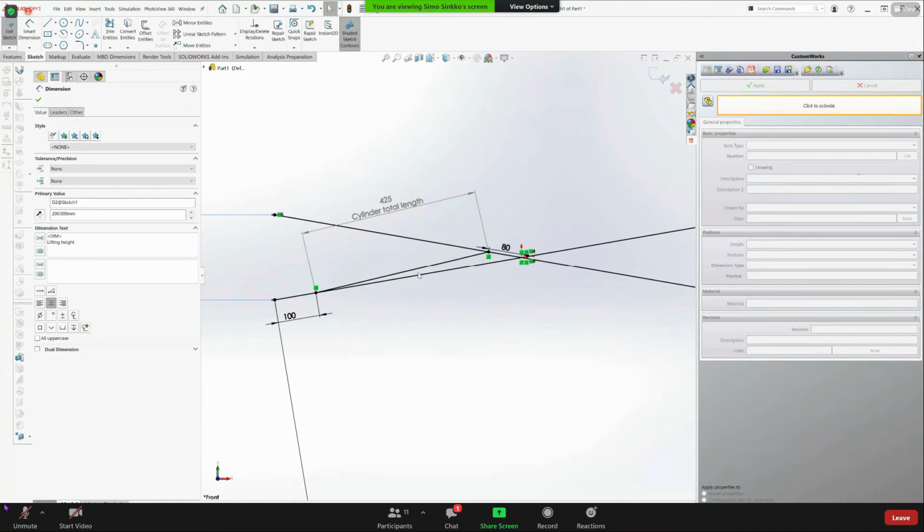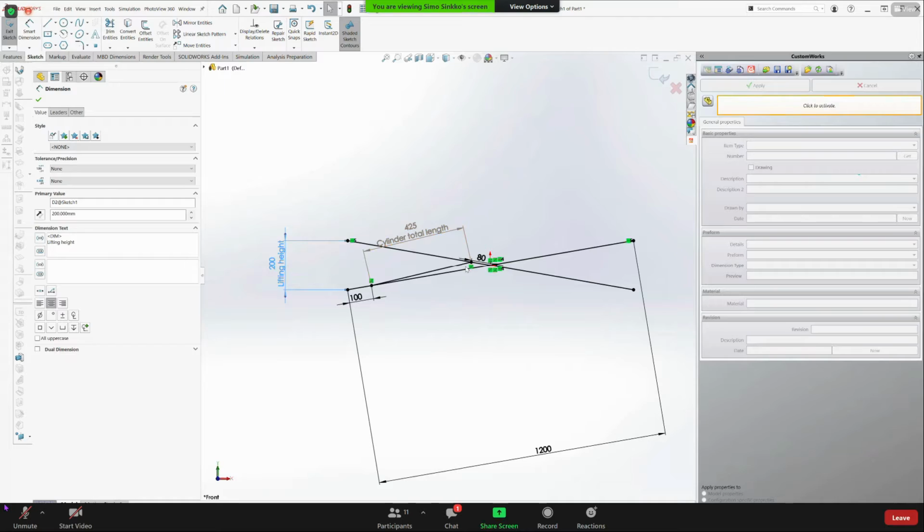If it's in a very horizontal position, then we need much more force, because in real life it's only the Y component that is used to lift this scissor, and the X component has no real use. Is the X component eliminated by friction, static friction of the scissor legs? I think we don't need to take care of this friction in this problem at all. Okay, just for curiosity. Yeah.